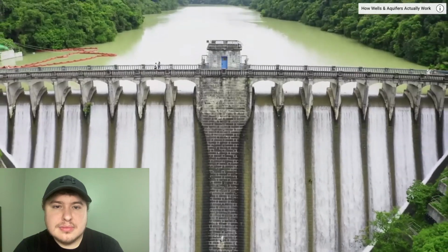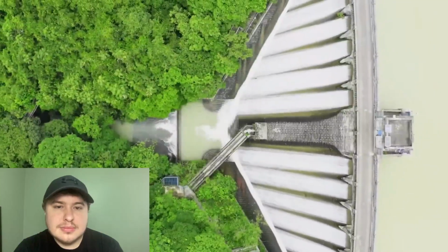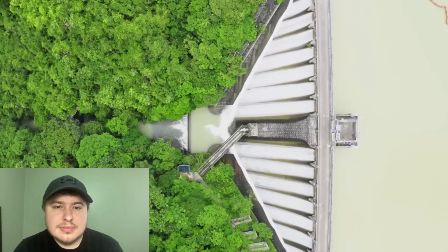Groundwater has always been a little mysterious to humanity since it can't easily be observed. It also behaves much differently than surface waters like rivers and oceans, sometimes defying expectations, as I've shown in a few of my previous videos. One of the most important places where groundwater shows up in civil engineering is at a dam. That's because groundwater flows from high pressure to low pressure, and a dam, at its simplest, is just a structure that divides those two conditions.